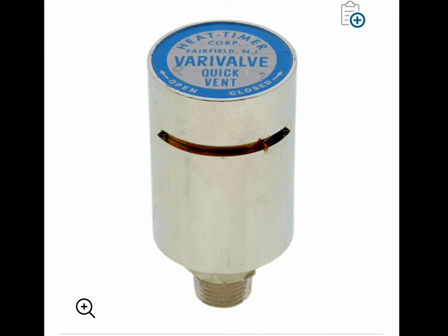The first reason why I don't recommend using this on a radiator, and I remember when I first encountered having one of these in the home that I lived in. If water so happens to get inside of your radiator and it makes its way to the air vent, the most this thing has inside of it is a thermostatic element. And the only thing that'll cause that thermostatic element to lock out is temperature. So if steam hits the element, yes, it'll lock out. And even at times when it does that, depending on this, you'll see water literally spitting out of this for the first couple of seconds, which can be rather dangerous, which is why I'm really kind of skeptical even about putting them on riser pipes if you have it facing toward the public.